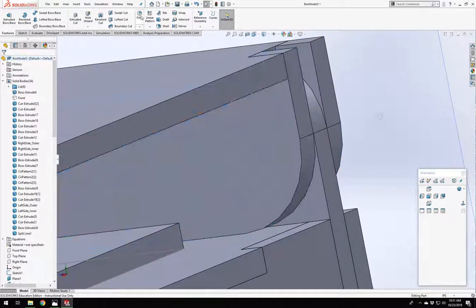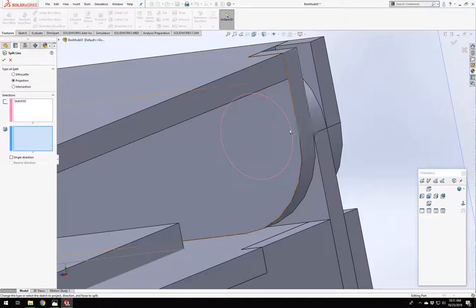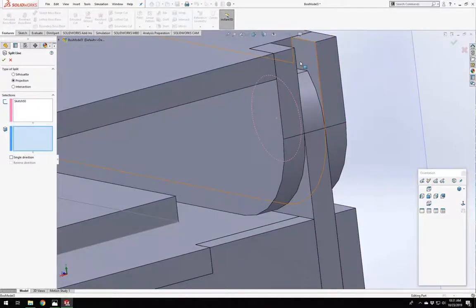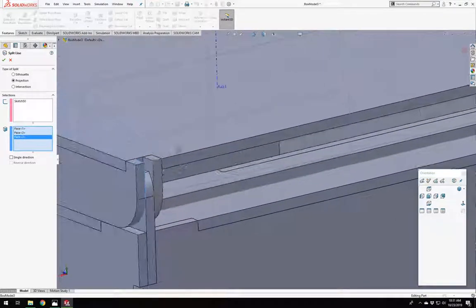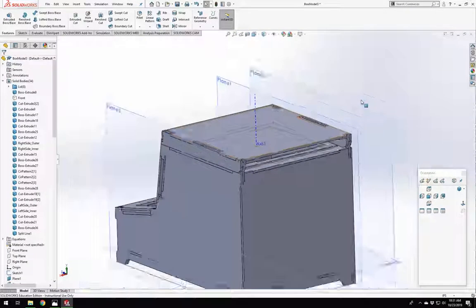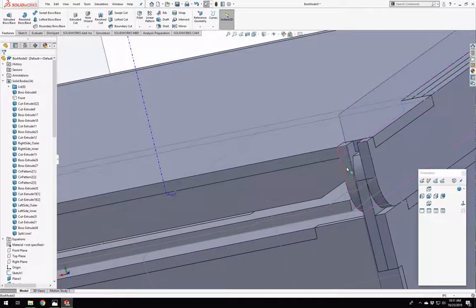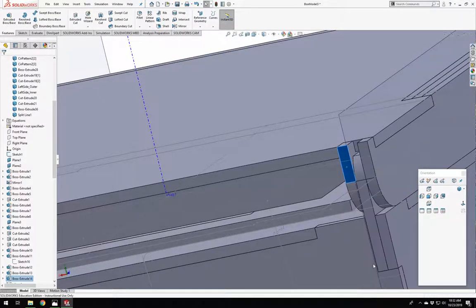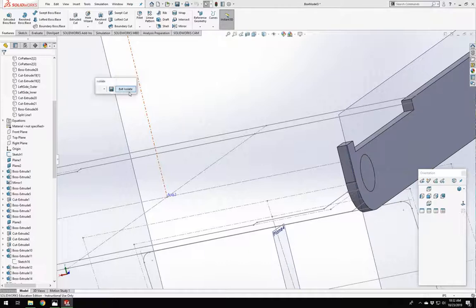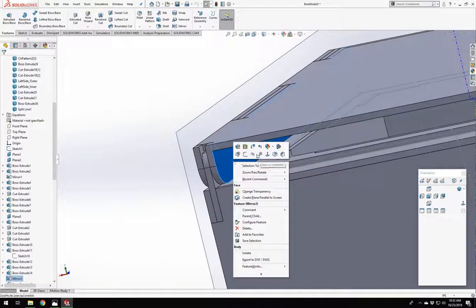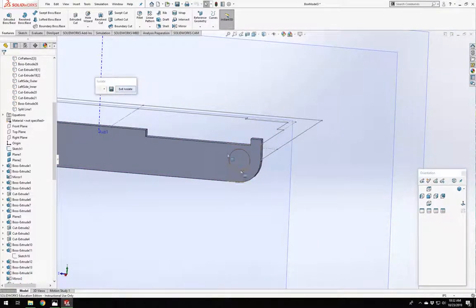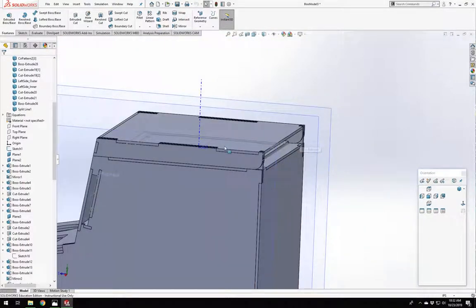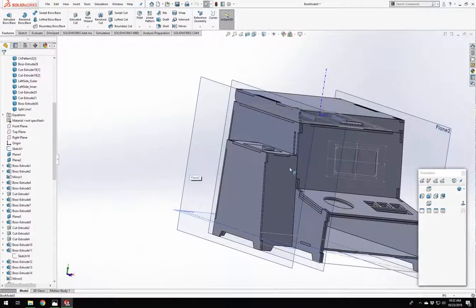There we go. So now we're going to do a similar split line of that selection on this face and that face and that face and that face. We'll see if this works the way I want it to. Cool. So now if we just look at this part, I'm going to do that isolate again. We should have that ring there. Same thing goes for this one on that side. So that will help us just place that piece back in, and so it'll be in the right spot so the hinge will work properly. Cool.